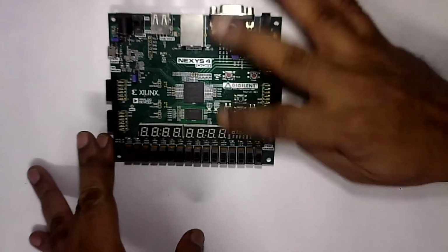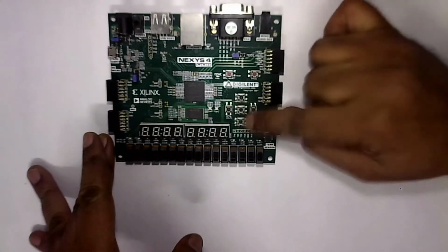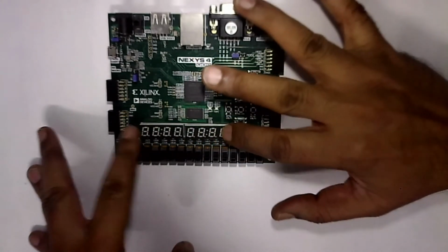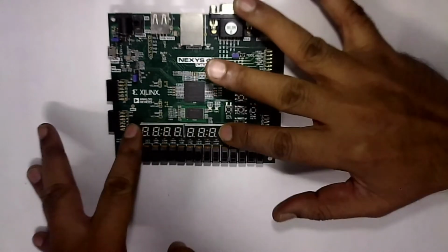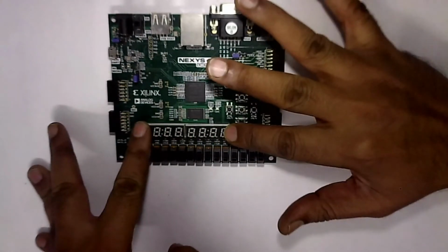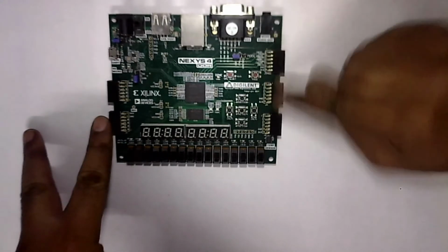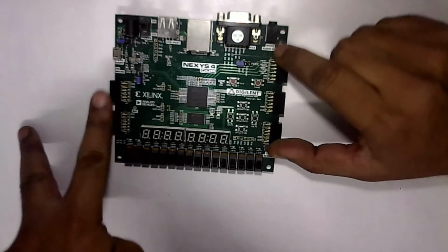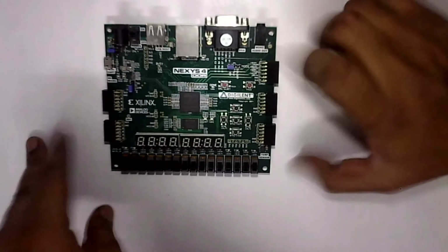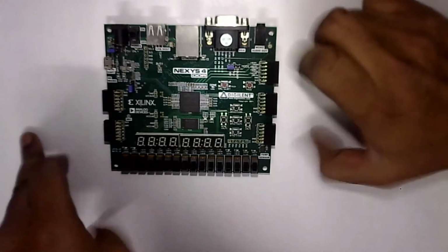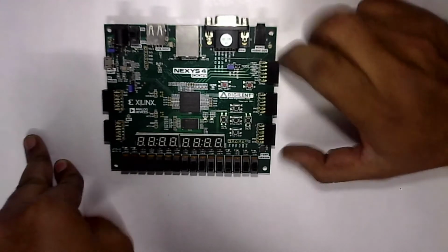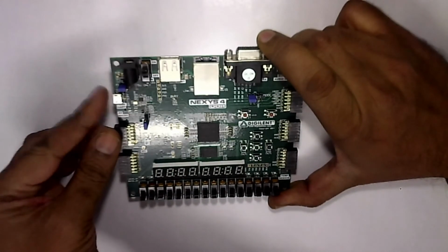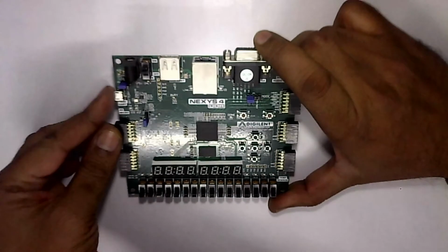Besides that, there are 5 switches over here, and these can also be used as inputs. And then there are 2 seven segment displays over here, right? So they can be used for displaying values here. Besides this, there are 3 PMOD connectors here, and 2 over here. So these are for the extension of the board to various other hardware, like for example motor drives and stuff like that. Now this board can be programmed using this micro USB type C connector.